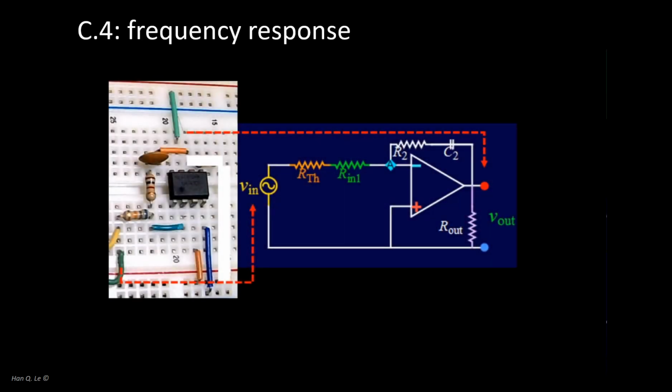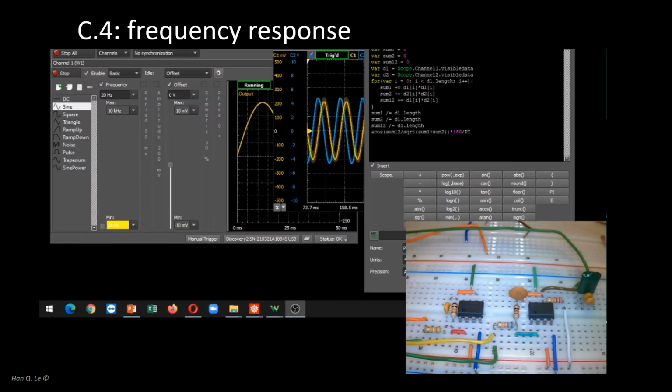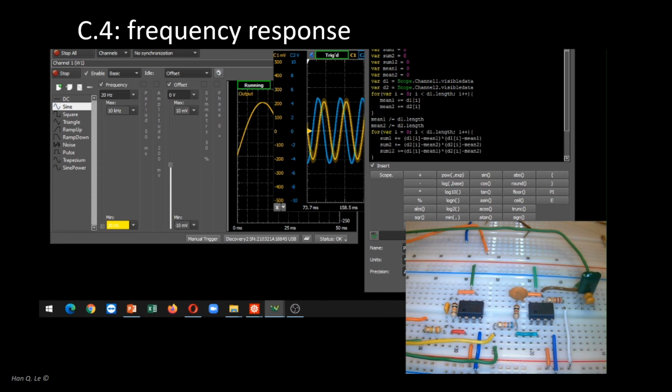The experiment was set up such that data can be acquired over the range of frequency of interest. Although the data will be analyzed with a computation app, appropriate measurement functions were set up to monitor the experiment and ensure its validity, especially the phase, for sanity check. The input signal amplitude was chosen such that the output amplitude is within the measuring range of the AD2 scope.